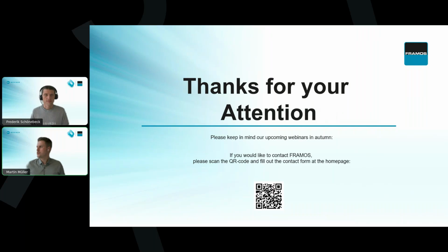The calibration for the 678 takes place in our imaging lab at Framos. At the end, it's a single color correction matrix, a 3x3 matrix. That's the final result. But to get to this result, we at Framos apply several different light sources with different light color temperatures. There's a way how to do that, which is not officially available, so you need to have some internal know-how and even support in the ISP toolchain. But the general approach is: take different light sources, take the same color pattern.